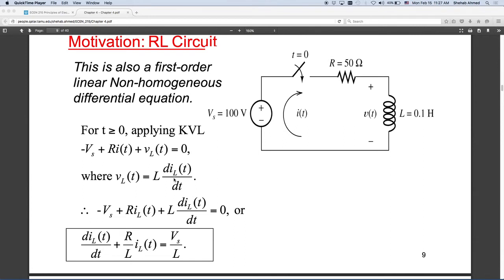So here it's the same thing. Inductor will, in this case, be as if it's a short circuit. The voltage across it will be zero. It's like a short circuit. Current will flow. So inductors will look like a short circuit for a steady state source after a long time. But as soon as you switch it on, what's happening? As soon as you switch this switch on at t equals 0, you have a transient response, a period of transient response. Was current flowing before?